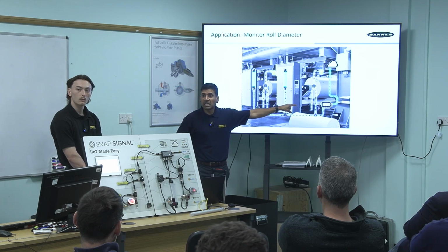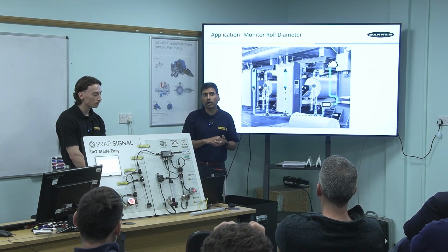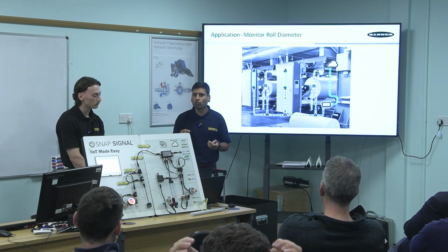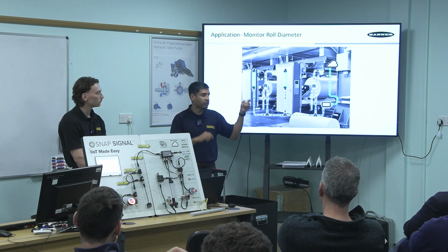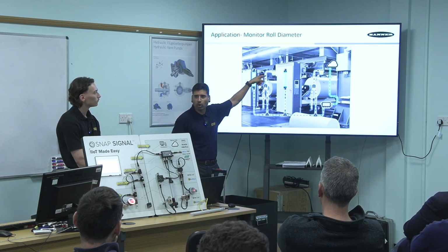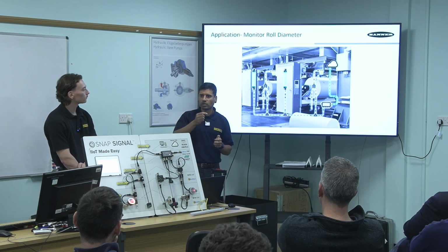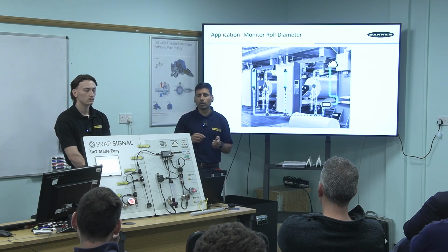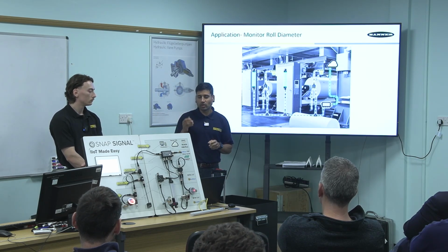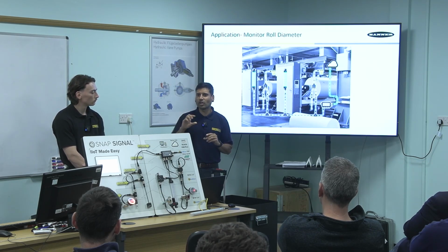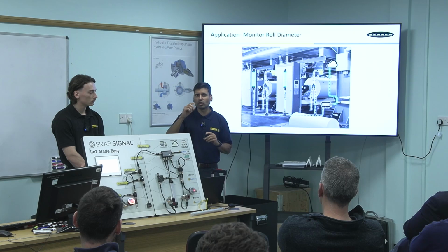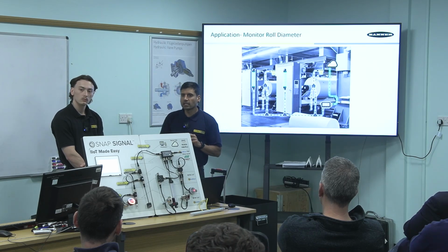So that's programmable. You can program it via simple read-write rules, which is you read from Modbus ID1, and then a write would be to write to a light output. Like I said, you could use the read-write rules, which are very basic statements. But you can also use a read-write rule like a lookup table.